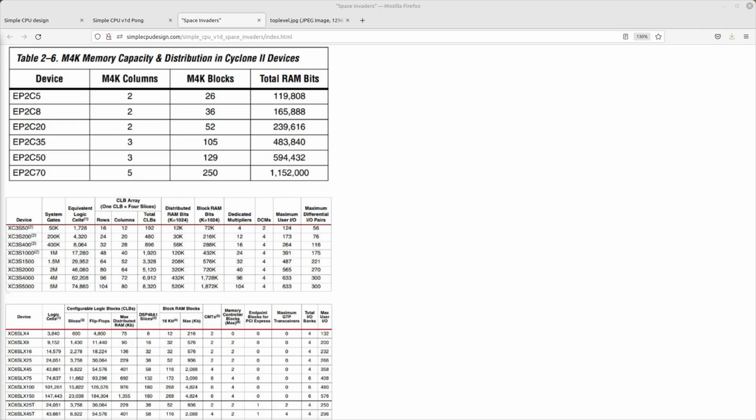You can't necessarily use all the hardware resources that are available on the chip, owing to routing constraints. You can see the figures in these tables are indicating the number of bits. For the Xilinx devices, those are block RAMs. So if you roughly divide by 10, you get into your bytes area. For your cheap FPGAs, you're looking at around 20 kilobytes worth of internal memory. And obviously some of that has to be used by the processors.